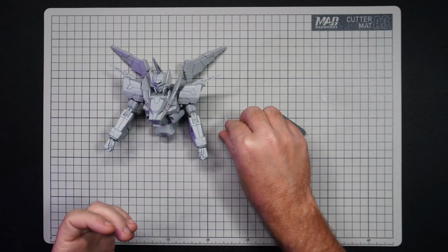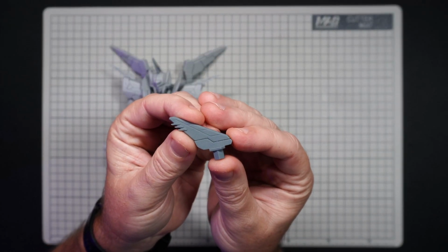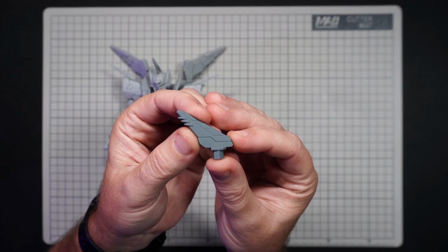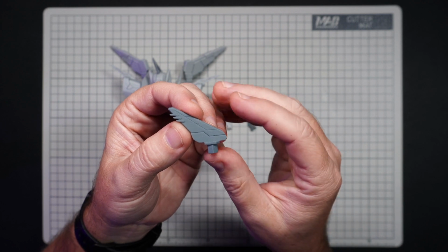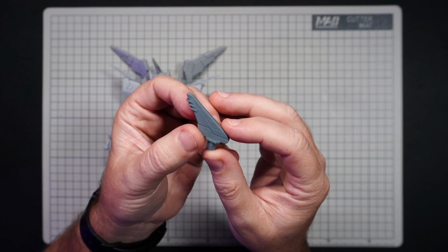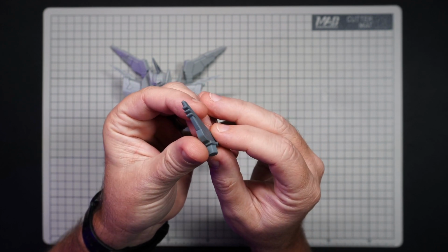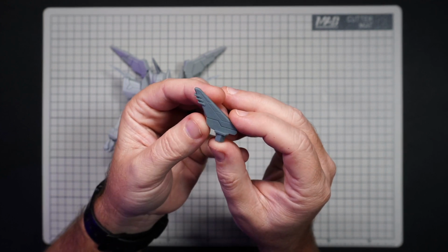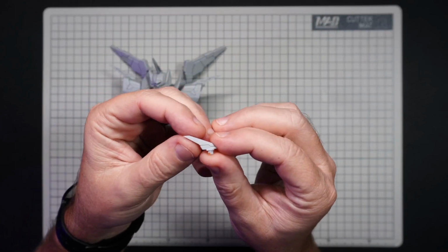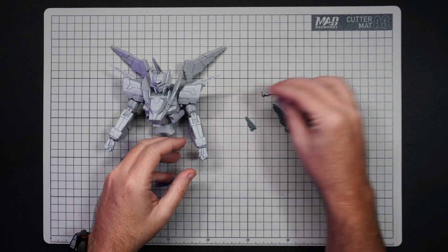Now, just to give you guys a better look, I actually also printed a version of this part at twice the size, so 200% scale. So here you can see all of those little details. And on that smaller version of the part, if we were to, like I said, sand it down and hit it with a coat of primer, a lot of this would pop out as well. But you can see all the nice little chamfered and beveled edges that we added and how those came out on the print. And they're making it look much more like a real part, as opposed to this one, which is just a shape with very squared off edges, right? So that's kind of the difference for me looking at these parts.